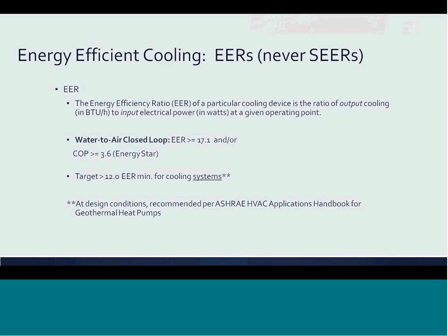For cooling efficiency in Sacramento, we would use the design temperature of 90 degrees. If an hourly or 8760 analysis is performed for a particular building, this information, along with the system efficiency calculations for all varying entering water temperatures between 35 and 90 degrees, may be determined. This information may then be compared to a similar bin or 8760 analysis for an air source heat pump or even a central plant system.